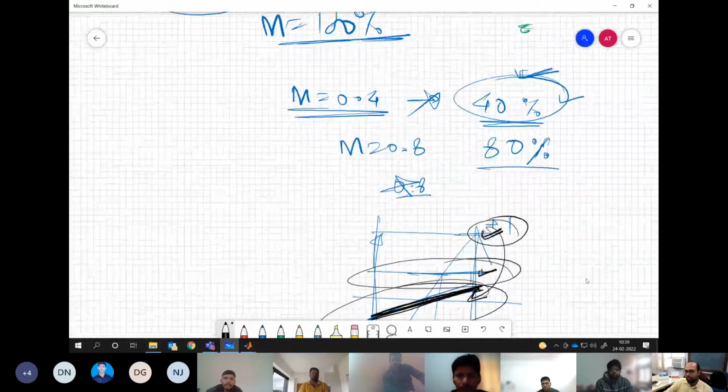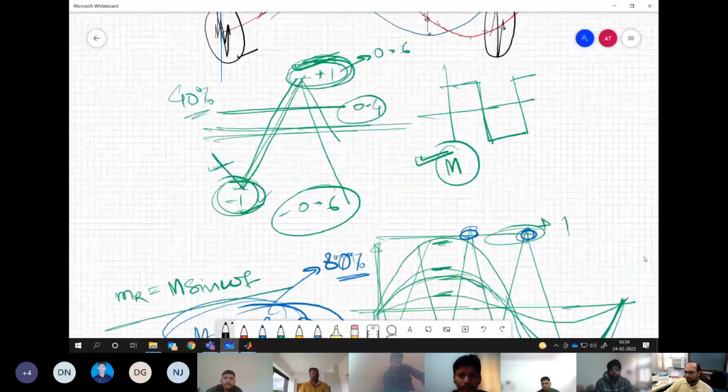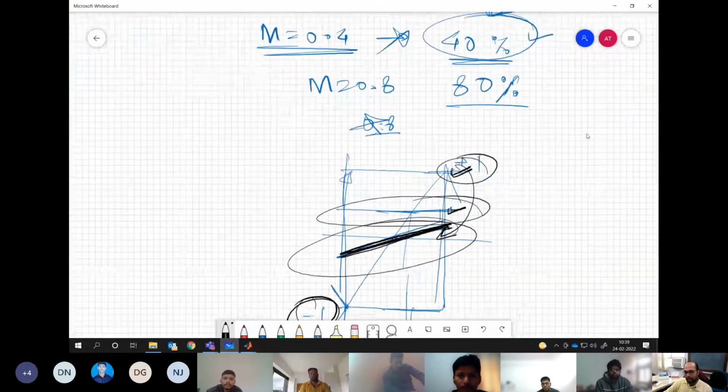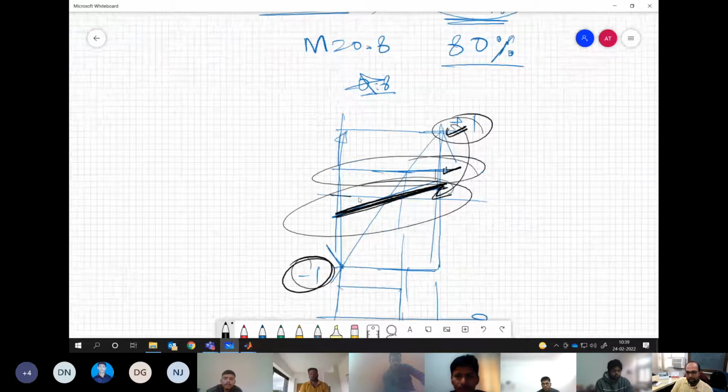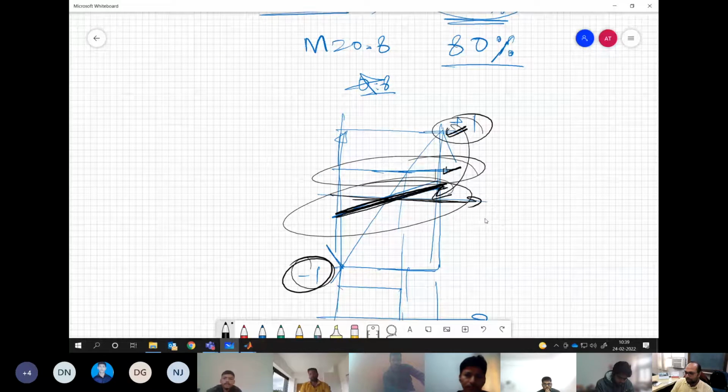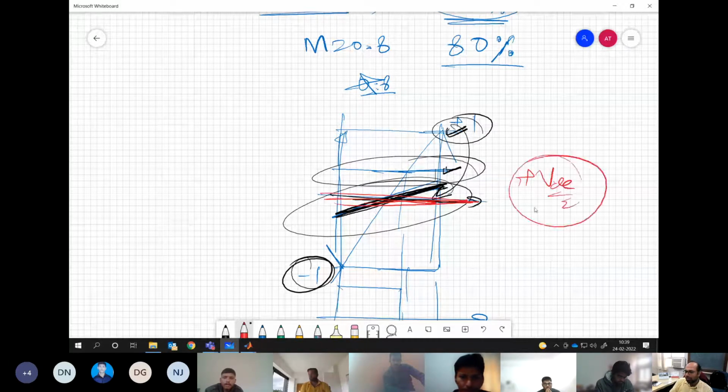What's the problem? You bring down your carrier to 0. You say, okay, I'm always getting plus Vdc by 2, irrespective of my modulating signal. Of course you will get. That's why I asked, why not 0 carrier? Why 0.8? Make your carrier 0. It is always plus Vdc by 2. Solved.